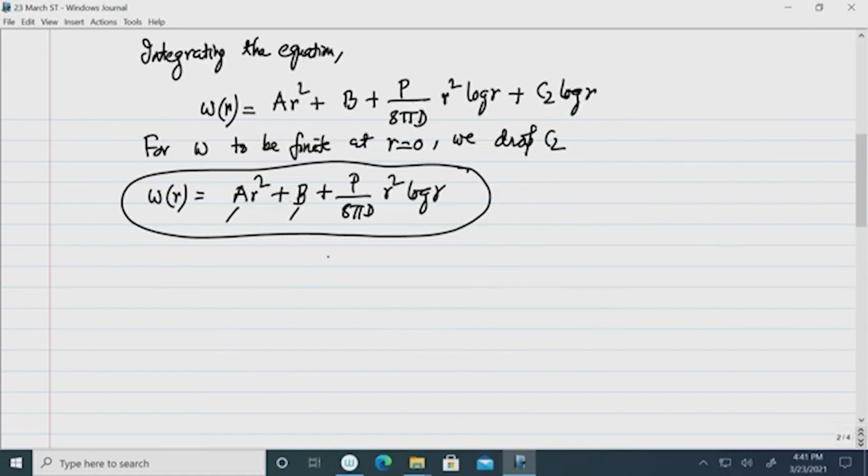That means, the equation can be rearranged in this form, final form, and then we apply the boundary condition. So, boundary conditions are at r is equal to say a radius a, r is equal to a, at the boundary, the deflection is 0 because it is simply supported, as well as M_r equal to 0.